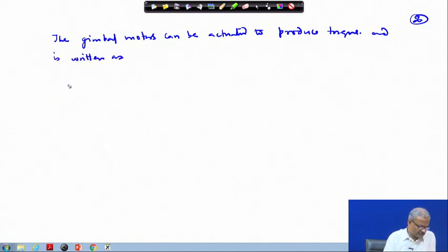So the gimbal torques are written as u w 0 0, we can write like this in the F frame. Your angular momentum of the body, here in this case the wheel, is an angular momentum in the absolute reference frame, and this is changing, but everything has been converted to the body frame. So this is written in the body frame.